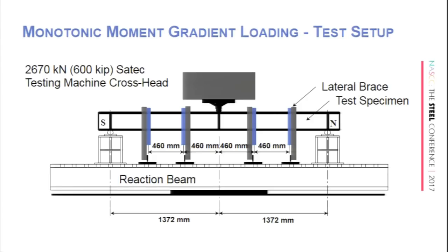There was actually an earlier requirement within AISC that if you were doing plastic design, there was something called Lpd. For the more experienced people in the audience, you might remember the term Lpd. Lpd said you have to have a brace spacing less than Lp to be able to do plastic design. So the brace spacing in these experiments was set to Lpd to ensure that we would not get lateral torsional buckling before we achieved full plastic loading on the beam, and to see how far we could carry that to determine what the rotation capacity would be in the experiments.